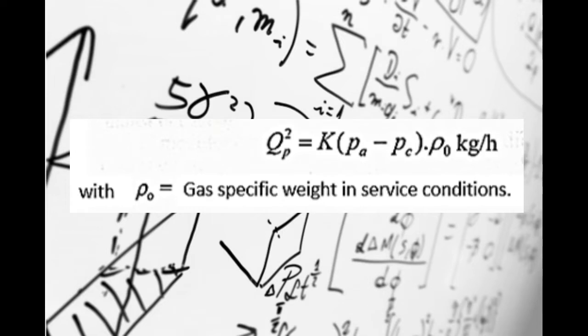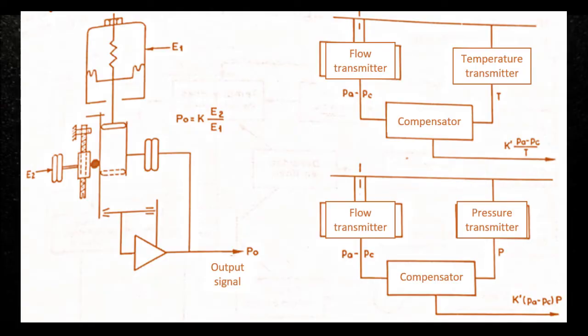In gases, the simple formula is equal to that of liquids because the expansion factor can be included in the K. Various systems can be used in electronic instruments. A compensating unit multiplier-divider that works with a differential pressure transmitter, a PPI absolute pressure transmitter of 4 to 20 mA DC, and a TCI temperature transmitter, and that compensates the flow of gas for temperature and pressure variations. You can make manual corrections for a specific gravity and compressibility.